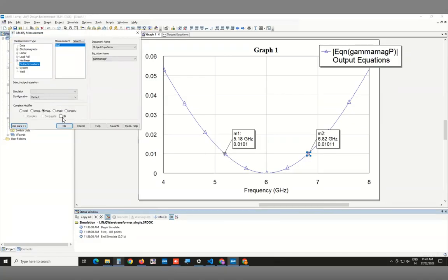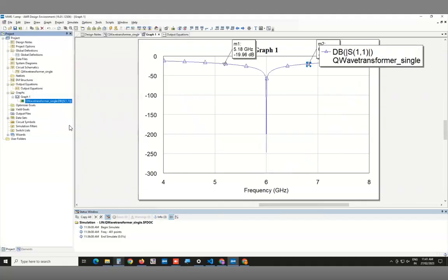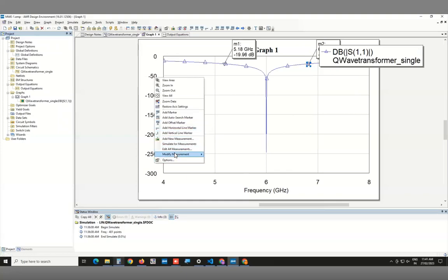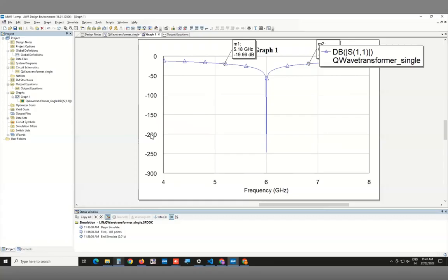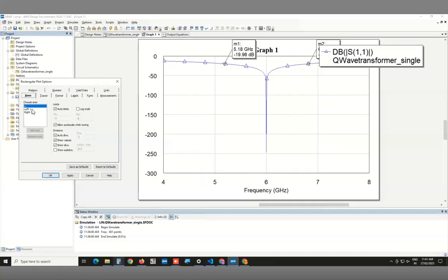The same thing, if I now look in dB and I go back to my standard port parameter, S11 mag dB, right? So because of this minus infinity, the thing auto scales terribly. So we just have to fix this by adjusting the axis. All right. So let's go to the left axis, remove auto limits. And we know 1% in dB is minus 20 dB. So let's maybe go up to minus 40 dB here.